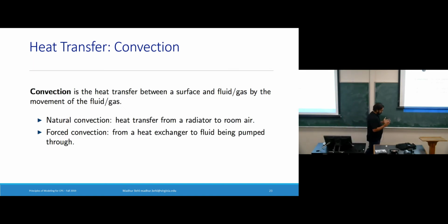Simply put, convection occurs between a surface, where we can define what a surface is in just a second, and a fluid. So unlike conduction, where it's the agitation of molecules literally colliding with other molecules of the substance and making this heat flow, in convection, the molecules themselves have this energy, and they physically are moving to a different location in the fluid to transfer heat, right?